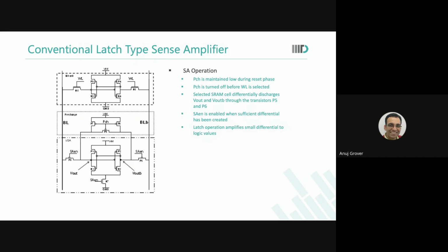Now, if you look at it, the bottom latch looks very similar to a memory cell. Is it not? Okay, there is one extra footer transistor somewhere there. Otherwise, it looks very similar. There's one more difference. One is the footer transistor, and second, these pass gates are no longer NMOSes. These pass gates are PMOSes. Why PMOSes?